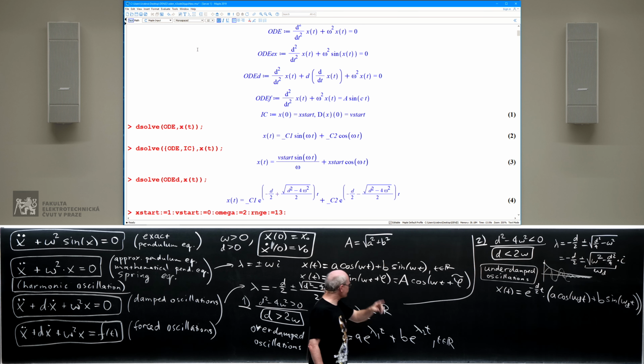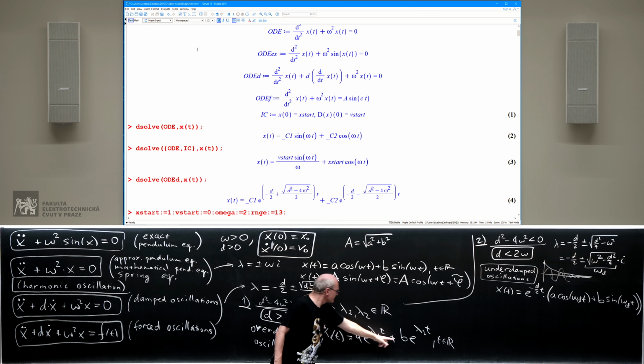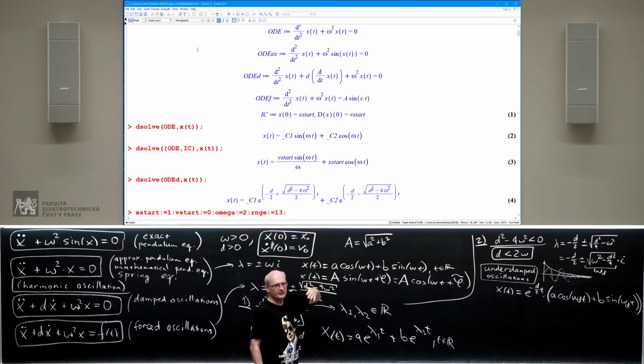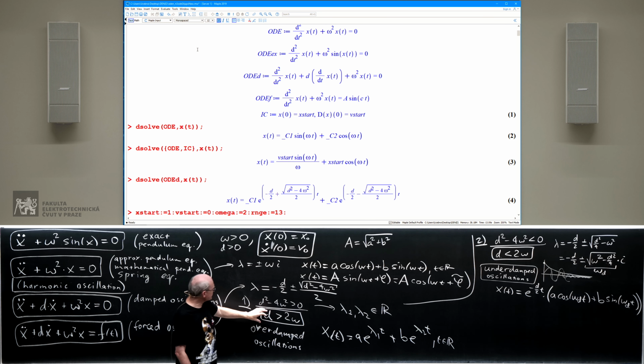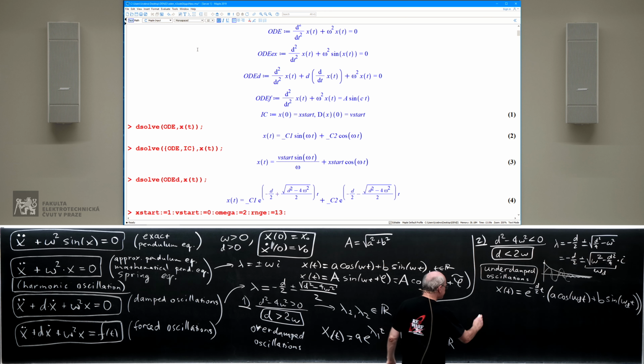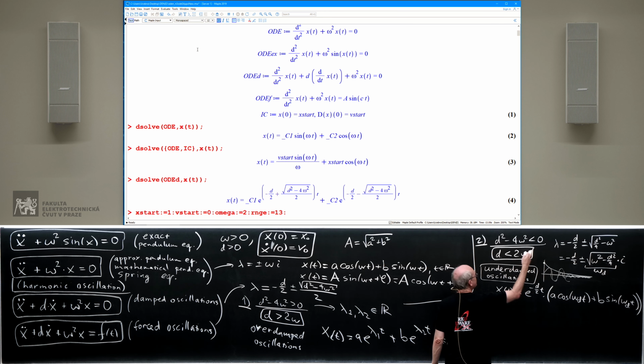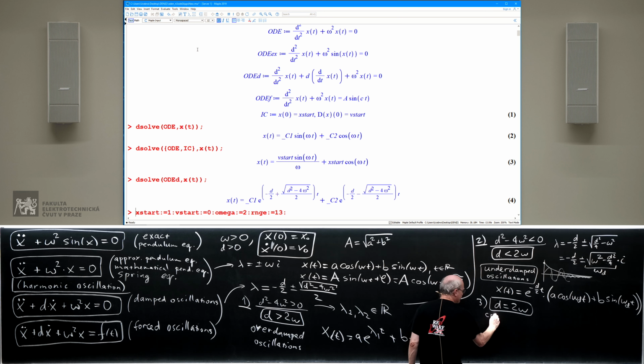If the damping becomes really strong, then you just get two exponentials combined, no oscillation happening. So this is a totally different thing. Once you start damping too much, you kill the oscillation. Now, of course, there is a third case, when you have equality here. d is equal to 2 omega. This is called critical damping. I should be careful. So it's critical damping.